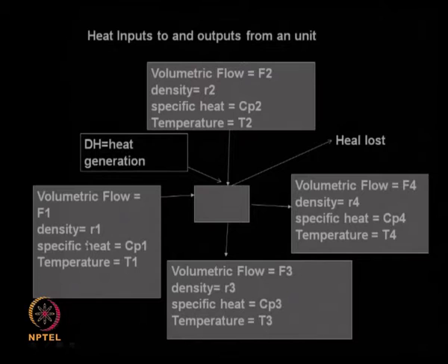Now let us look at the heat content of a fluid that is coming in. This will be equal to the mass of that fluid that is coming in, times the specific heat of the fluid, times the temperature corrected at a certain datum condition. So m Cp delta T is equal to the total heat. This we have read a long time back.